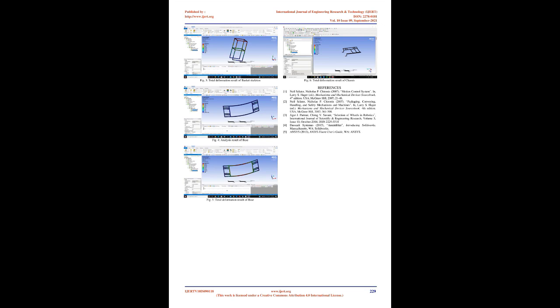Measures taken to overcome them. Conveyor belt mechanism was decided due to the ease of stopping the ball, and we don't need to control the robotic arm. We decided on a seesaw-shaped mechanism to stop the ball if it is coming while rolling on the ground, and a goalpost-like structure with net to stop a ball coming in projectile motion.